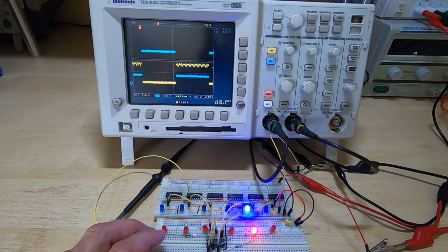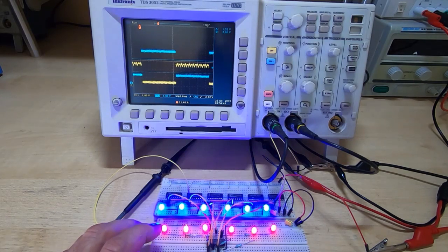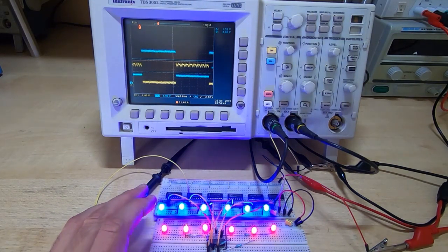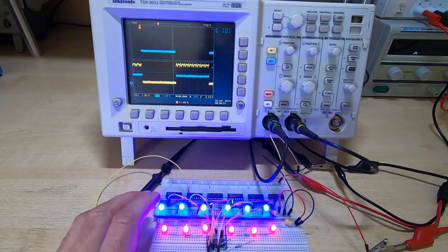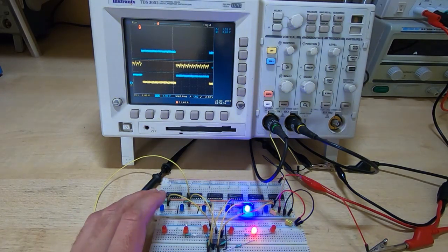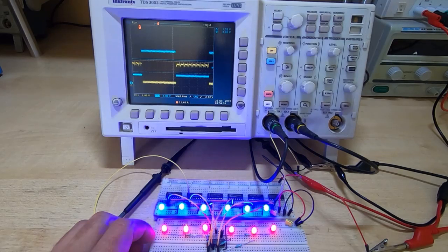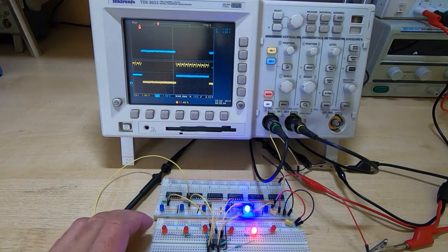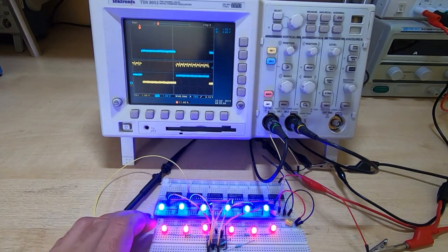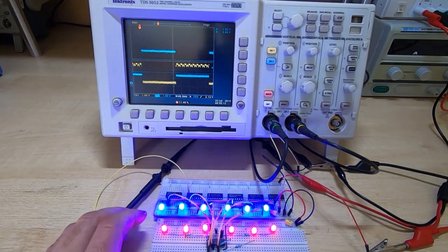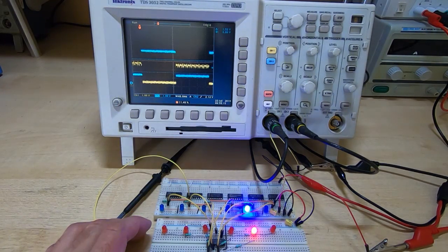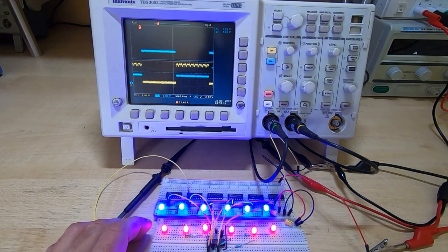So with the Altair it looks like you're getting problems caused by noise, which is what I thought I was looking at when I first got this Altair, until I started going through the board and then finding this mismatched collection of devices. Once I replaced those, the entire machine started becoming much more stable. Still very noisy, and that's the thing I'll be investigating in future videos, but this is the first thing to do if you suspect you've got noise issues on your Altair: make sure that you haven't got a weird collection of devices plugged into the cards.